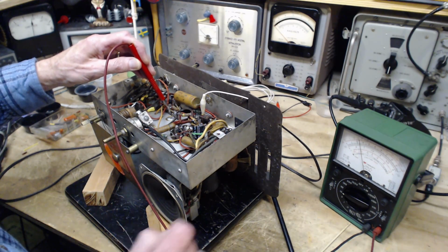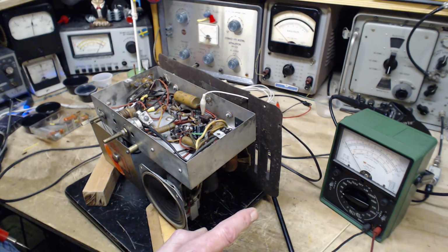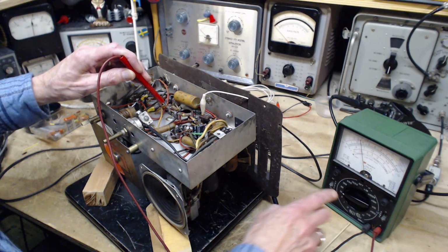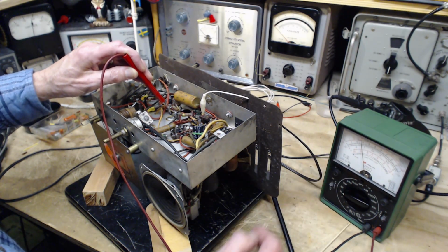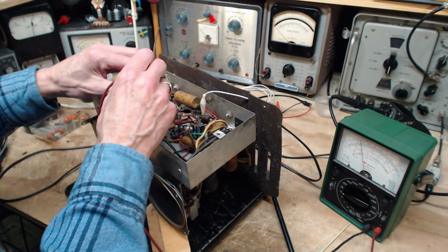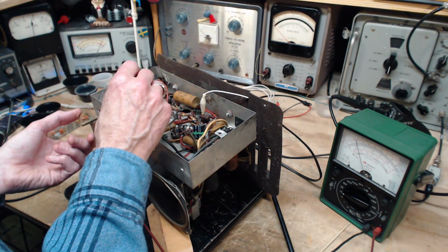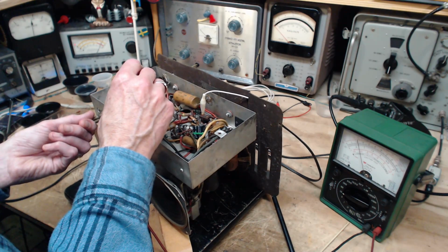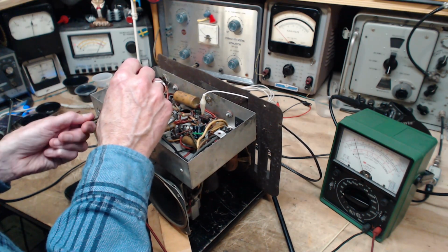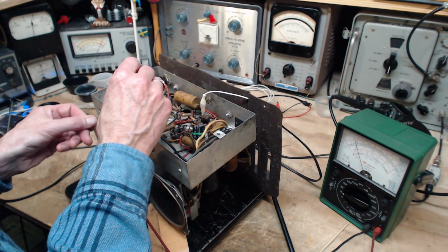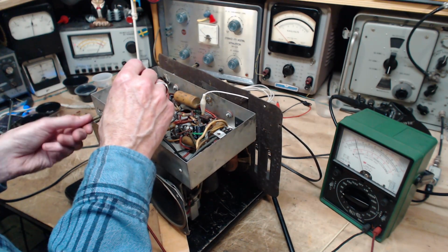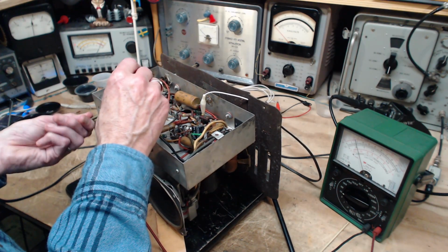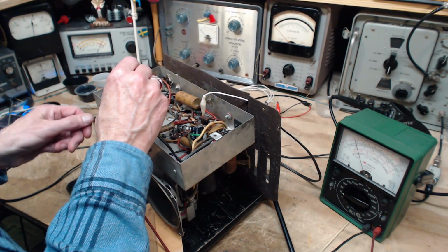So we're introducing some interference, that clicking interference, which I can't really hear now. Voltage is around 3 volts. 3 volts negative. Now if I tune the radio, just touching the chassis is doing that. Okay, hanging on tight to the chassis and tuning around. We're getting no AVC voltage action here. Up in the oscillating area.